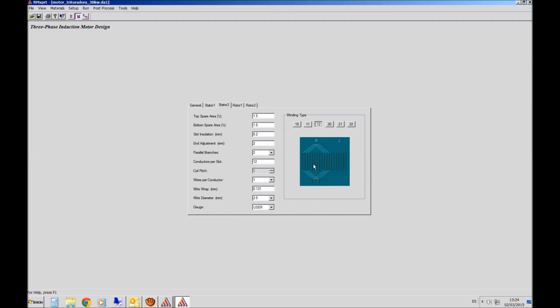So this machine is a machine with a concentric type coil, so we don't need to define anything. We only have to choose this type of arrangement. In the other cases, you see you've got different types of connection, but well, concentric is good enough. So this is the design we are going to apply. Well, let's go first to these parameters here.